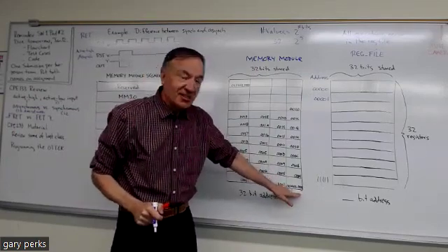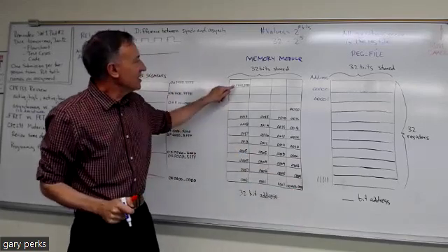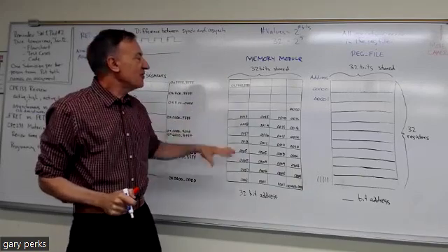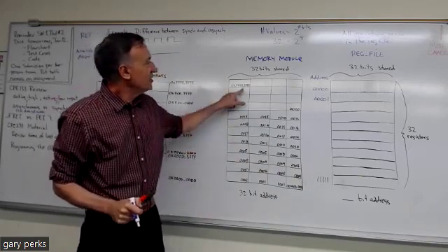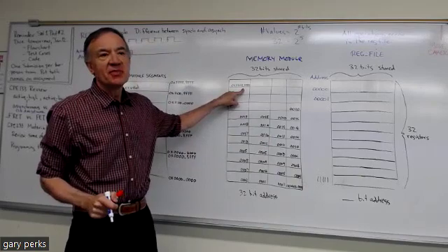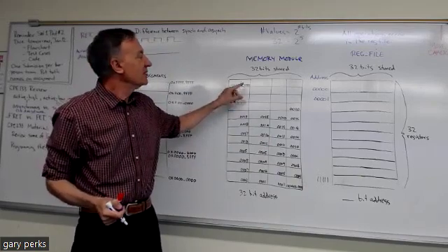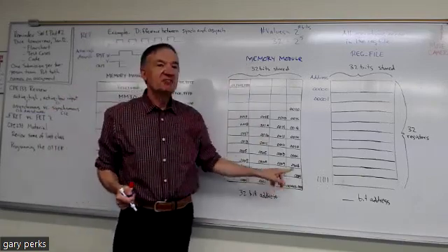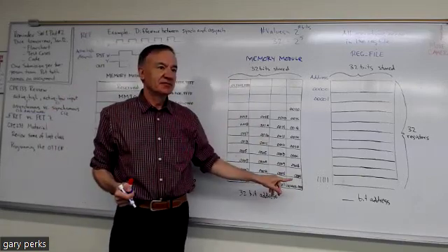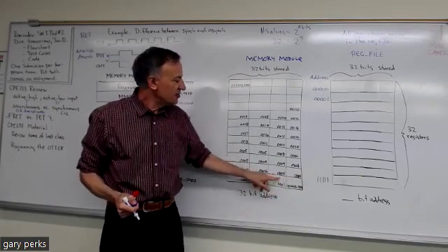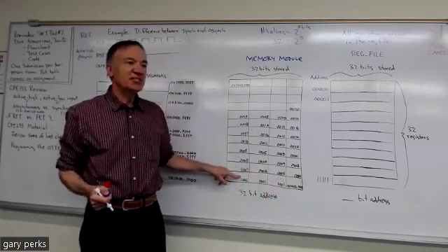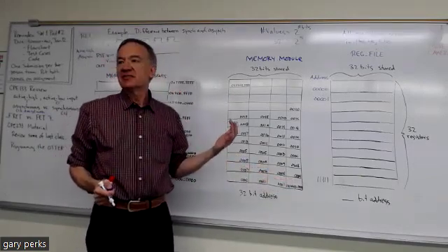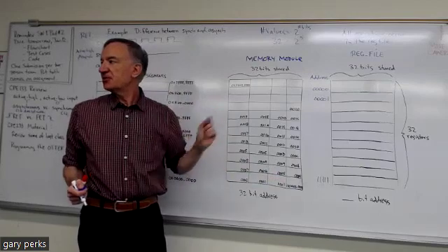So we start at all zeros and we end up with all Fs. You could figure out how many registers there are if you took this number and divided it by 4, because remember we talked about last time that the memory module is byte addressable. Each 32-bit register has 4 bytes, because a byte is 8 bits, so divide 8 into 32, that's 4.